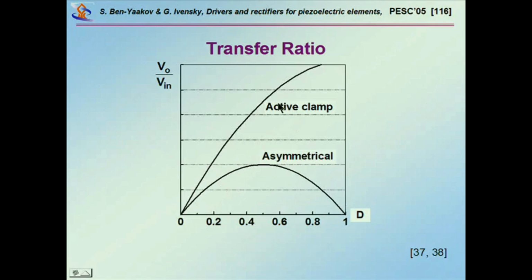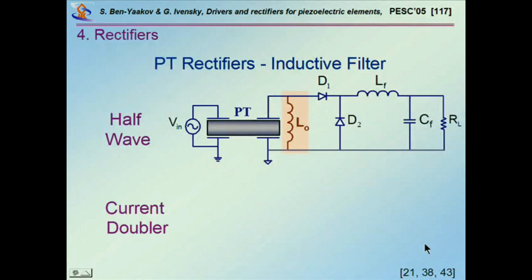If you use the active clamp, however, because you are building up a higher voltage, you keep going with the output voltage, and you actually generate higher voltages, so it's nice that you get the full range, and in fact, as I've said, the gain factor on the piezo element, which is kind of a neat way to go. Some people, I guess Professor Ninomiya and some others, worked on it, and these are the reference here. That's not our work.